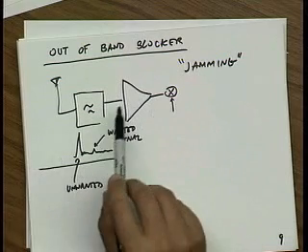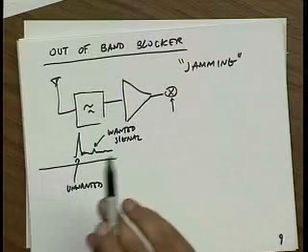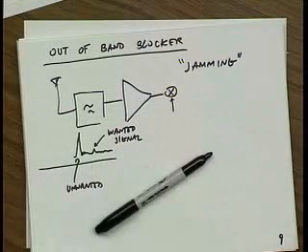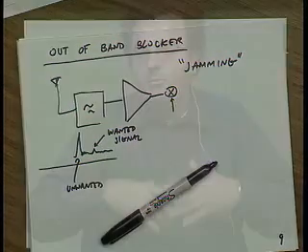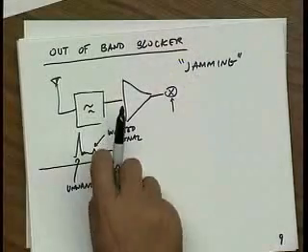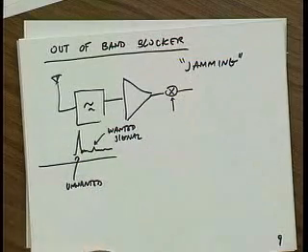This is a really bad situation because we don't really have control over what comes into our amplifier, right? If you're in a laboratory and you're doing a very careful experiment, you're very delicate, you buy triax cables, you hook everything up, you do shielding, and so you only pick up, let's say, your measurement data. That's fine. But what if you're out in the real world? If you just stick an antenna out, there's no way you can control what people are transmitting into space. So you're going to pick up everything, all the junk. And it's very likely that some of the junk that you're going to pick up is going to be stronger than your signal. Okay? So let's see how jamming works.